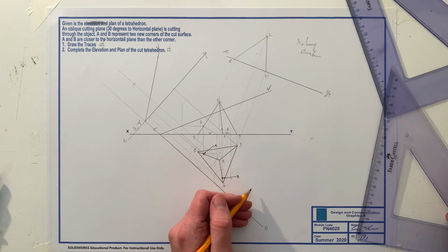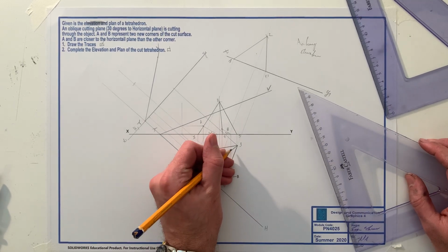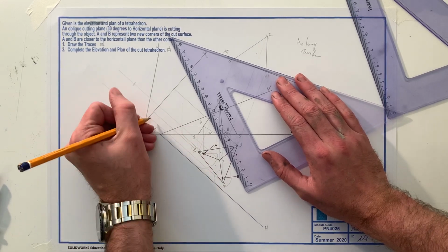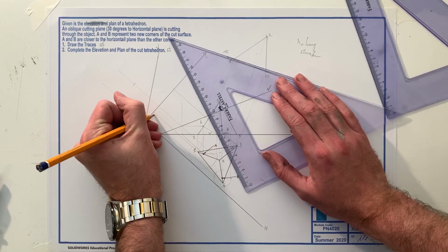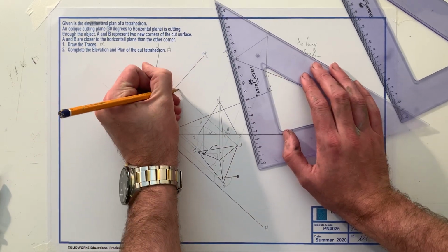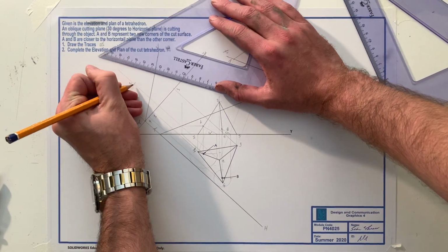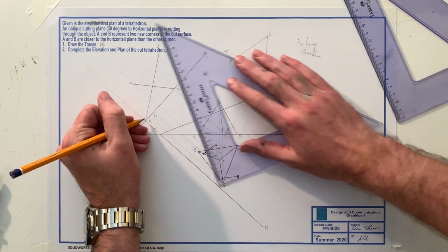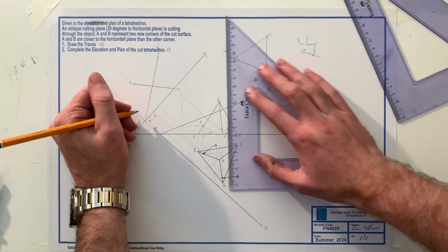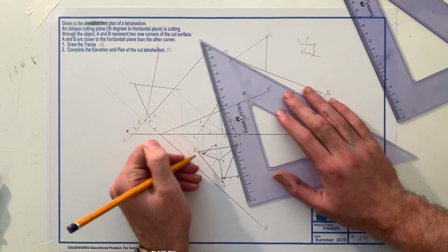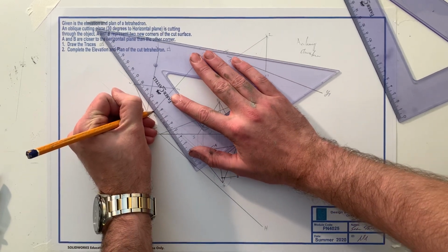So what we're going to be doing is like standing here. You can imagine all the lines here out in front are going to be the ones we can see. So we have our 4, which is here, our 1, which is here. This is going to be 2, and this is going to be 3. We'll be able to see 2 to 3. We'll be able to see 4 to 2. We won't be able to see 1 to 2, so I'll just put that in as hidden detail.